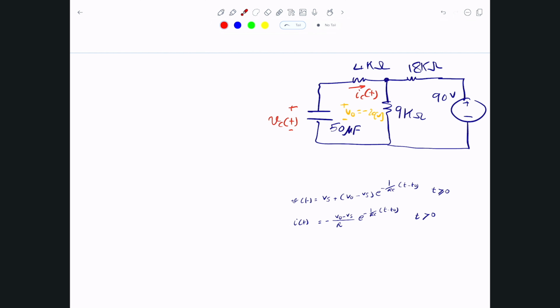But what we do know is these equations apply to a circuit that looks something similar to this. It will be like some sort of a voltage source, a resistor, and then a capacitor in series to each other, which is not the same as this circuit in here. Because, for example, which R should I be using? I have 1, 2, and 3. And the voltage source, well, I can technically use that, but anyway. So what happens is you shouldn't be using this particular circuit.